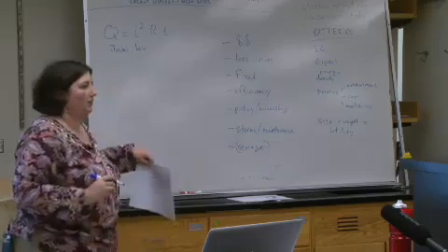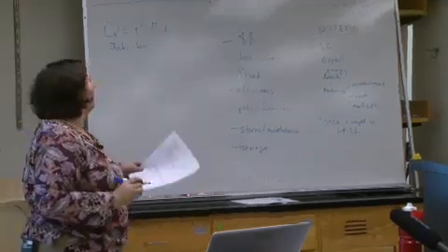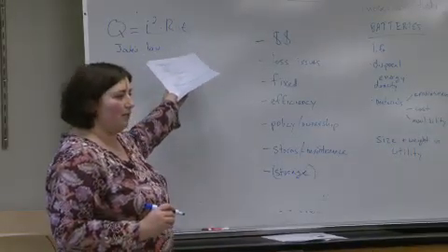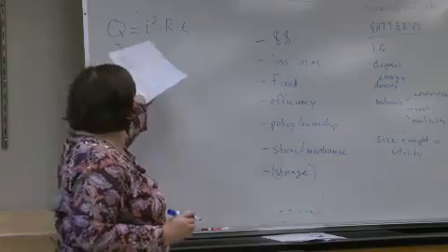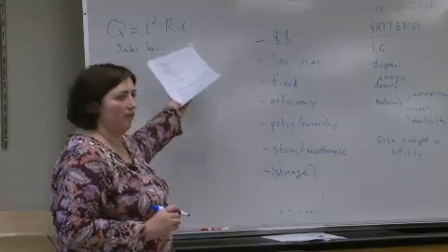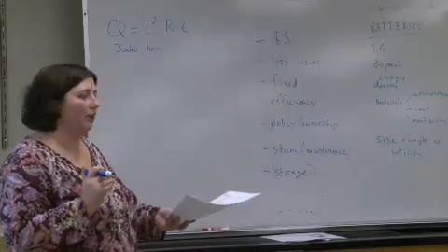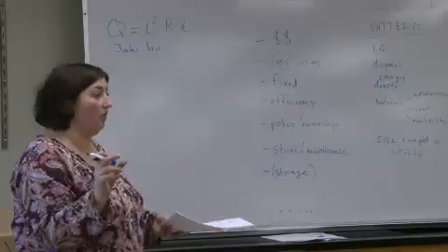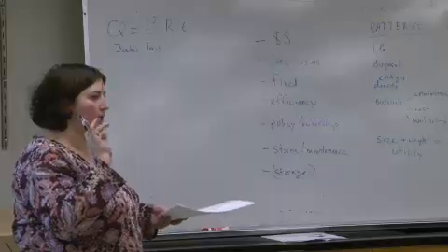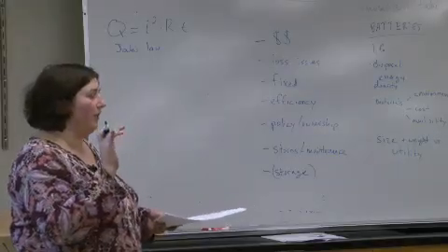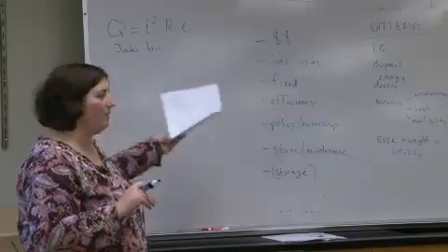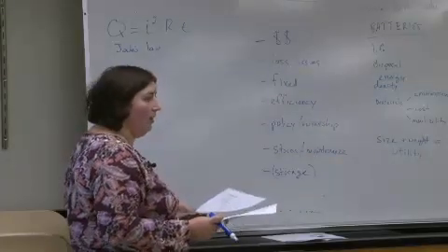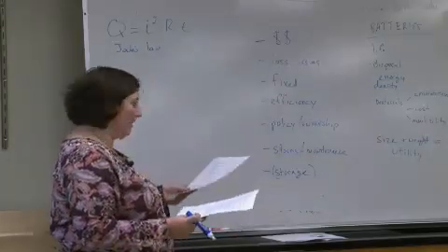And if you're not super comfortable with your double E, you're probably going to say, oh, well, the IR, that sounds like a voltage, and throw a voltage in there. And you're missing a subtlety, because then you say, oh, well, it's related to current and voltage at the same level. But you have to figure out what voltage you're calculating, because if you recall, while current is going through the whole wire at the same rate everywhere, because it's a flow, a voltage is based on a comparison of two places, and you have to compare the right voltage in order to plug that into the equation correctly. So we're not going to do that right now, but we're going to go through this equation in a little more detail, so hopefully it becomes a little more intuitive.